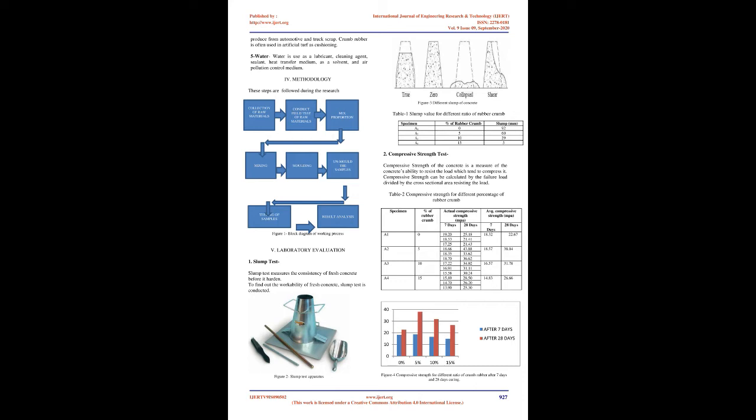The objective of the study is to test the properties of concrete when shredded or crumbed rubber is used as aggregate by partial replacement of natural aggregates. The parameters of this investigation include the compressive strength of concrete specimens, cubes of 150 mm x 150 mm x 150 mm size. M25 grade concrete is used for testing, and percentages of rubber aggregates are 0%, 5%, 10% and 15% of normal aggregates. The natural aggregates are replaced by rubber aggregates on a volume basis. The strength performance of modified concrete specimens was compared with the conventional concrete. The parameters of this investigation include the compressive strength and workability of concrete.